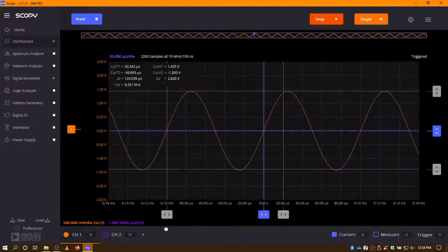Also, if I want to measure the frequency, move it over here, find out where it crosses the zero line, take that cursor there, move it across. It'll tell you the differences in the cursor locations, the time delta, and in turn the frequency. So those are cursor measurements. If you don't have a default measurement feature that will fit your needs, you can use cursors.